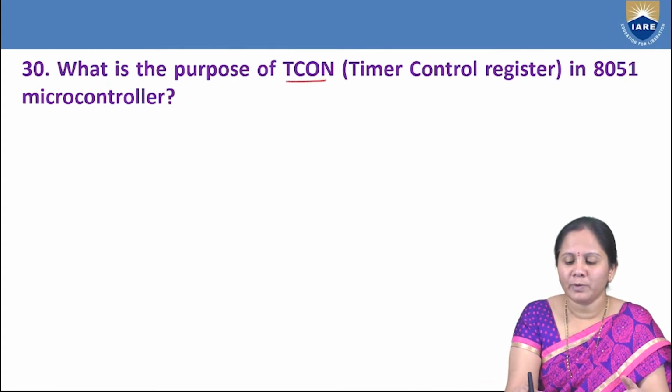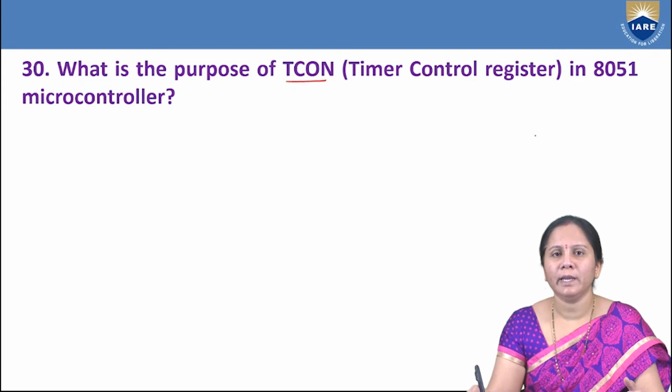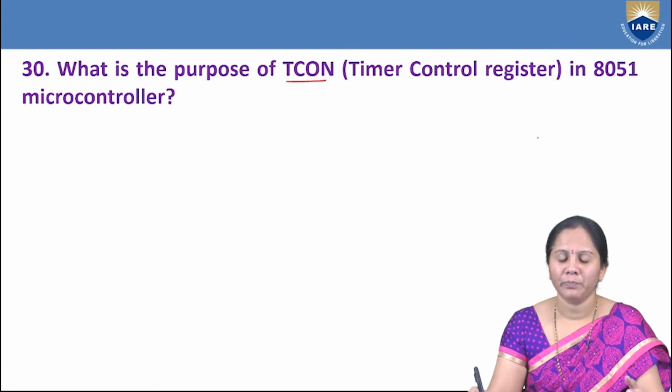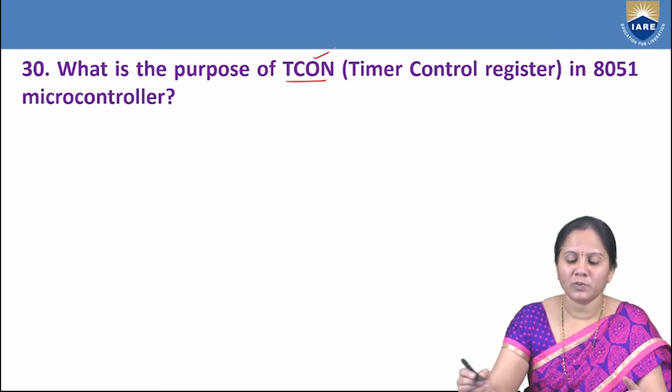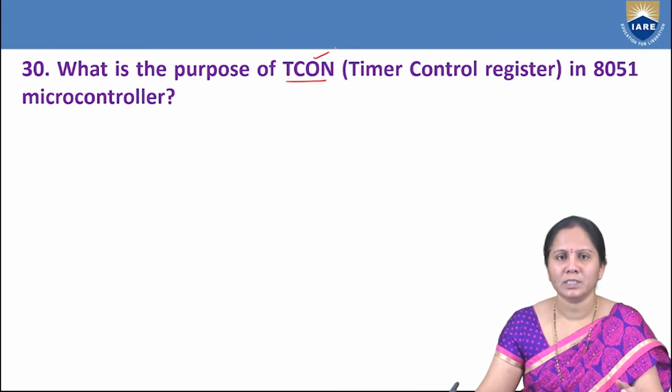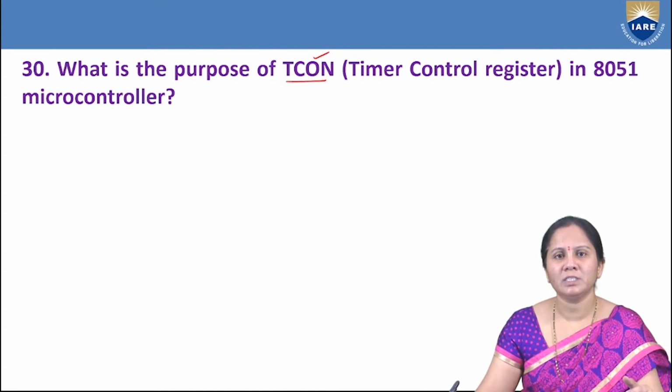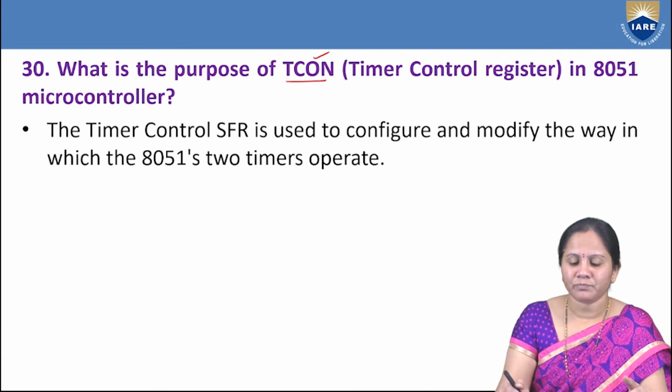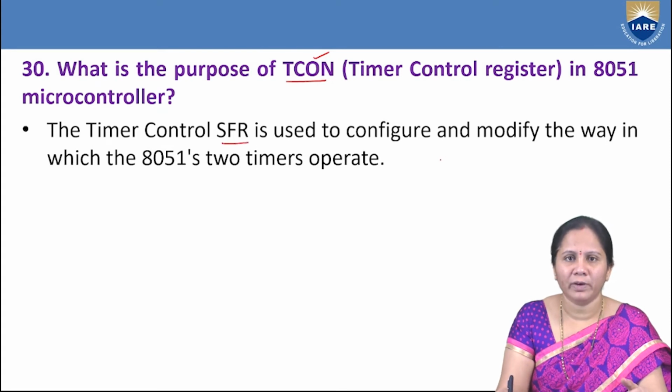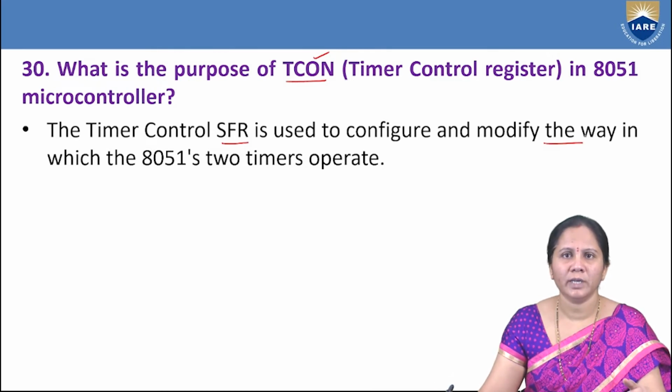Next, what is the purpose of the TCON register in the 8051 microcontroller? Here TCON stands for timer control register. This is one of the registers available to perform timer counter operations. This TCON register also comes under the SFR, the special function register, used to configure and modify the way in which the 8051 microcontroller operates.